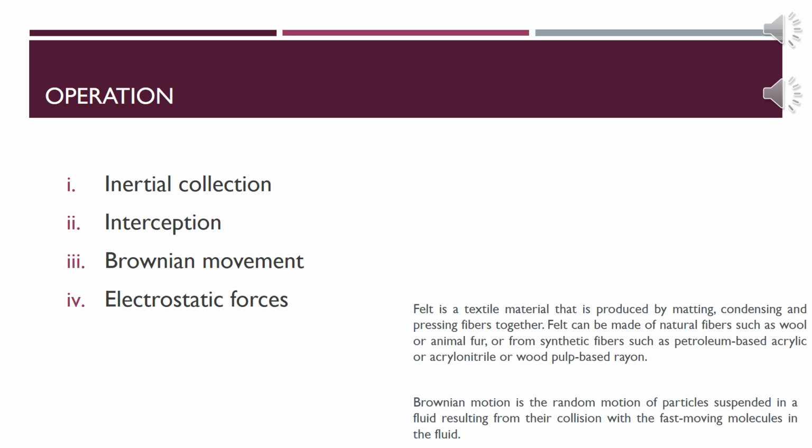Dust-laden gas or air enters the baghouse through hoppers and is directed into the baghouse compartments. The gas is drawn through the bags either on the inside or the outside depending on the cleaning method, and a layer of dust accumulates on the filter media surface until air can no longer move through it. When a sufficient pressure drop occurs, the cleaning process begins. Cleaning can take place while the baghouse is online, meaning it's filtering, or offline, meaning it's in isolation. When the compartment is clean, normal filtering resumes.